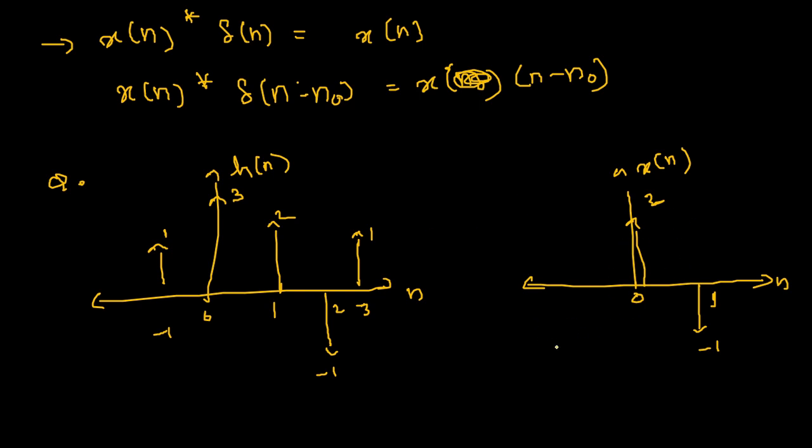So this method for convolution can be helpful when we have very few inputs. We can write h of n in terms of the unit impulse function, and we can write x of n in terms of unit impulse function. If your unit impulse function is shifted one step to the left, we write it as delta of n plus 1, right? And when the unit impulse function is exactly at 0 but has a higher amplitude, we simply amplitude scale it, so this is at 0 and its amplitude scaled by a factor of 3.